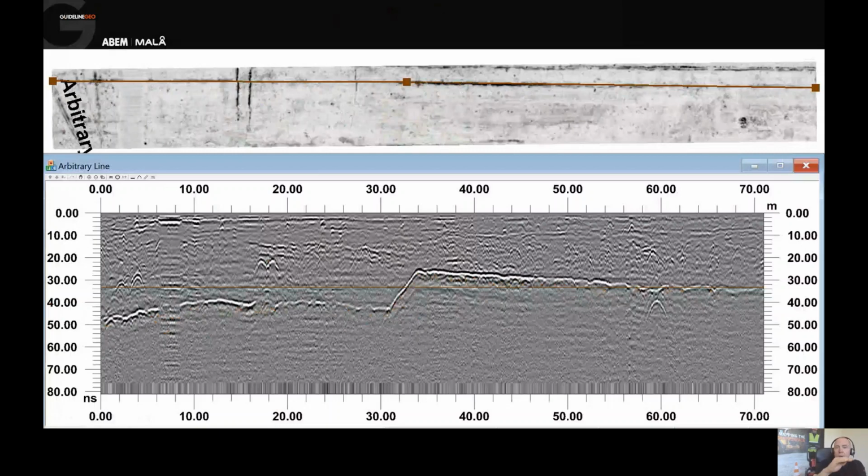Because Florida is so flat, quite often they will pressurize the pipework, the sewer itself, to force the contents along the road. So here we could pick out that utility, and there's a step here where it's rising towards the surface and dropping back down again. But we can actually see some other responses. I can see 3 utilities. There are faint responses in the data up here, which can be more clearly visible if I look up and down the data in the time slice. But we can see I've got 3 responses here, 2 responses here, and there are some responses further down the street as well.